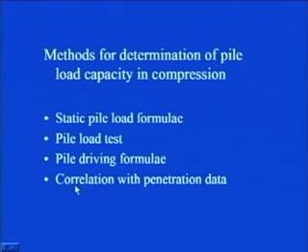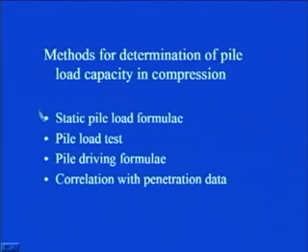And then there are some correlations which have been developed over many years using the penetration data. I hope that you have studied the standard penetration test while you studied the soil exploration chapter, and from there once you get the data, that can be correlated to the load carrying capacity of the pile in compression. So, these are mainly the 4 categories from where you can estimate the load carrying capacity of the pile. So, let us start with static pile load formulae, how we can find out the capacity of the pile using these formulae.